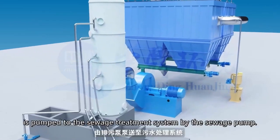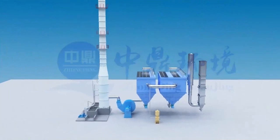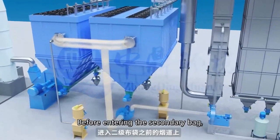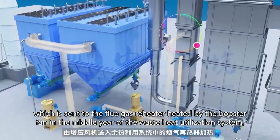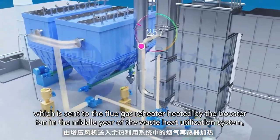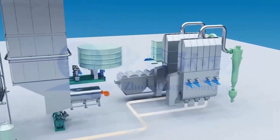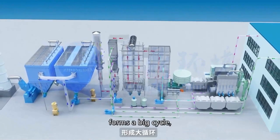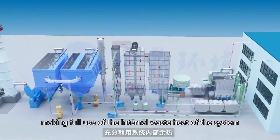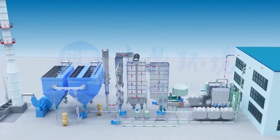Salt-containing wastewater from desulfurization is pumped by sewage pumps to the sewage treatment system. Some of the flue gas is extracted from the duct before entering the secondary bag filter. The flue gas sent by the booster fan is heated in the reheater of the waste heat utilization system, and then sent to the drying system as the fluidizing air for the dryer. Thus, a large circulation of drying flue gas is formed within this process system, fully utilizing the internal waste heat of the system to ensure high recovery and low energy consumption throughout the system.